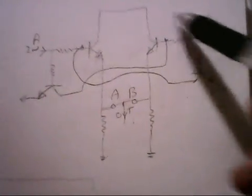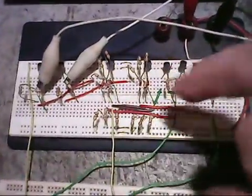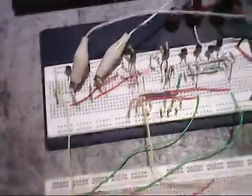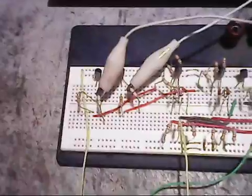So we need to build this circuitry here, tie it to two of these AND gates, 3-input AND gates, and then put that with the circuit here and see what we come up with. Run down here in the circuitry. This area here is the exclusive OR gate. These are the two AND gates, 3 inputs each. And because this circuitry here needs negative inputs in order to make the outputs happen, I had to put 2 inverters. They were just 2 NPN transistors. I have the switches. And so let's go ahead and put this to a test here now.